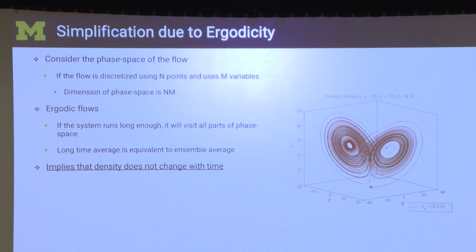This transition is important because, in our mind, if we think that the left lobe is the burning flame solution and the right lobe is the extinguished solution, let's say, then you can have a situation where, depending on where you start the problem or how long you wait to do something, you can either go to the left lobe, the fully burning solution, or to the right lobe, which is the extinguished solution. So how you start the solution, how long you run the calculation, all of this becomes important.